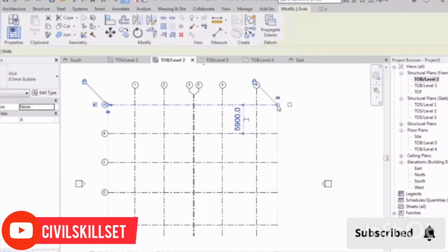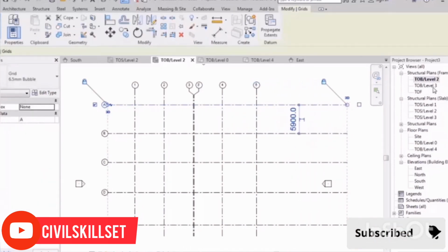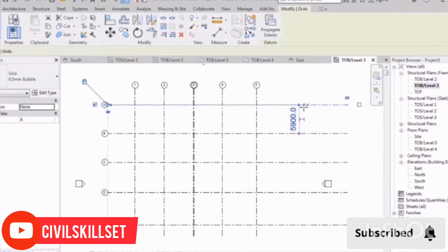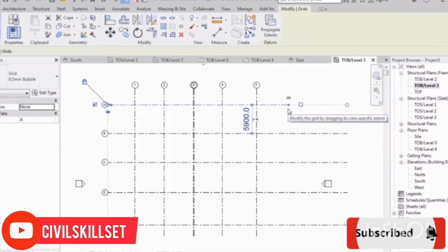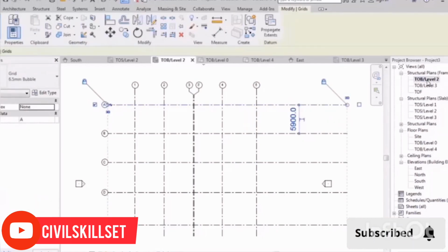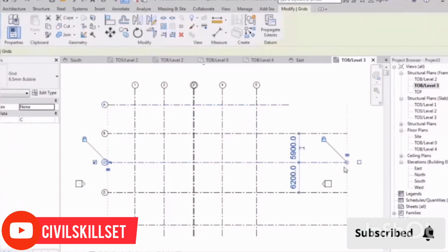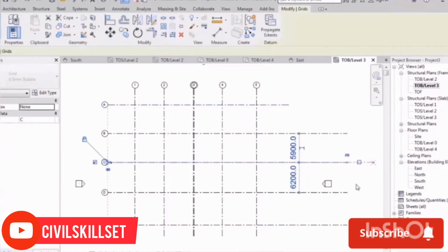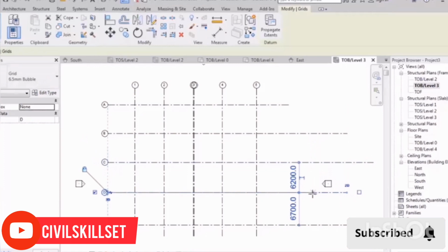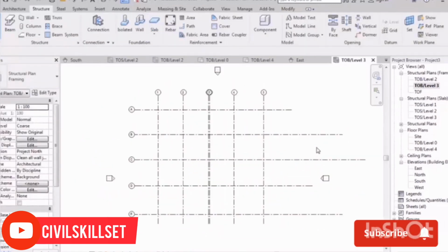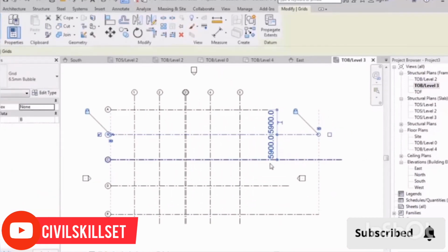But what about 3D? When it is 3D and you move it, you will see the effect in other levels. But when you change it into 2D and you move it, not only will it be moved alone, I mean the lock will automatically be opened, it will not affect the other levels. It just changes in this level, in this view actually. And this is not that good a thing. Why would we want to change the rhythm, right? It's useful sometimes, we will go for it.